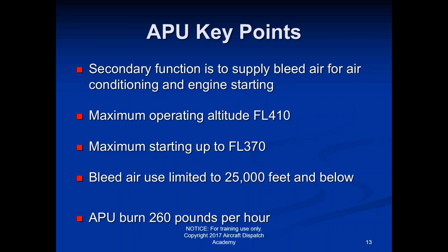But anyway, if we don't know about the issue before it gets there and they shut down their engines, then the plane is grounded, because it doesn't have any way of turning the engines back on. They'd have to get the APU fixed, or find somebody else at the airport who has an air cart, maybe the FBO or maybe another airline. But in the case where we're the only operation, the only flight in some of those podunk Minnesota cities, none of them have air starts, by the way, we are pretty much just dead in the water. We have to send a mechanic up to get the APU working, and it turns into a road trip, basically.